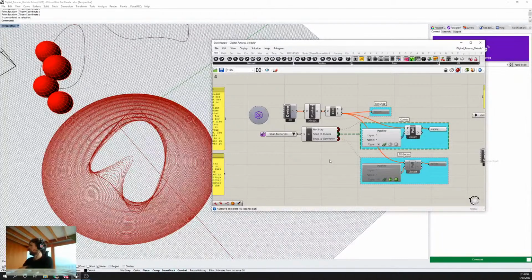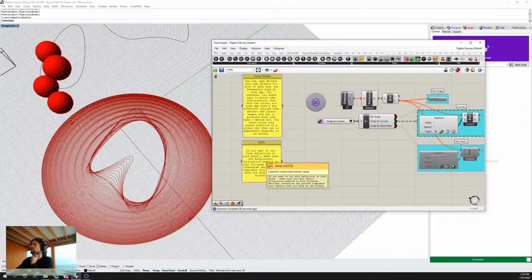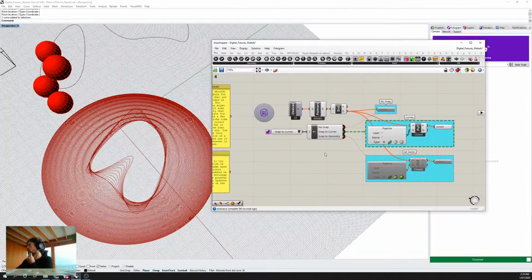So the default cursor on a mobile phone is, when you tap on the screen or drag on the screen, we're projecting a line out from where you're tapping until it intersects with the nearest detected surface in physical space. You can slightly change that cursor behavior in the Fologram settings, so you can have the cursor be always on and just projecting out from the middle of your phone, and also at a specific set length from your phone, depending on what you want to use that cursor for. But Fologram doesn't by default give you any control over, say, whether or not that cursor snaps to geometry. So that's something that you have to build yourself.